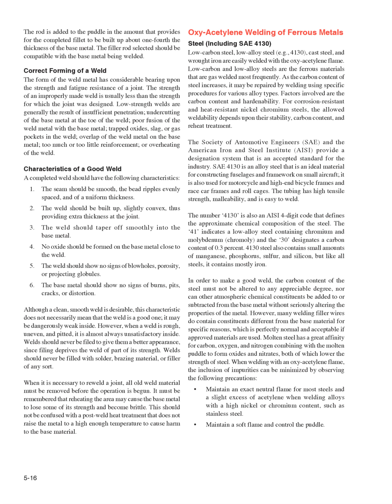Oxyacetylene welding of ferrous metal: steel, including say 4130, low carbon steel, low alloy steel, cast steel, and wrought iron are easily welded with the oxyacetylene flame. Low carbon and low alloy steels are the ferrous materials that are gas welded most frequently. As the carbon content of steel increases, it may be repaired by welding using specific procedures for various alloy types. Factors involved are the carbon content and hardenability.